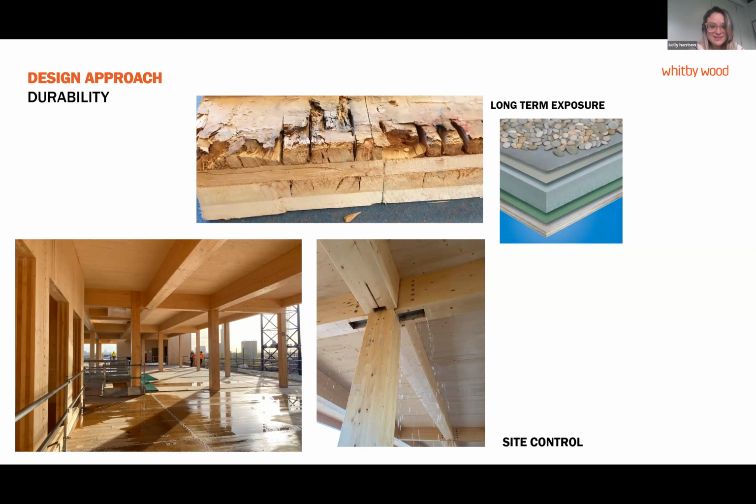And then also site control. So some lovely photos here of a nice wet site. First off, your floors, as long as they're taped up, it's actually quite difficult, unless you've got water sitting there for months on end, to penetrate through the top of the CLT slab.